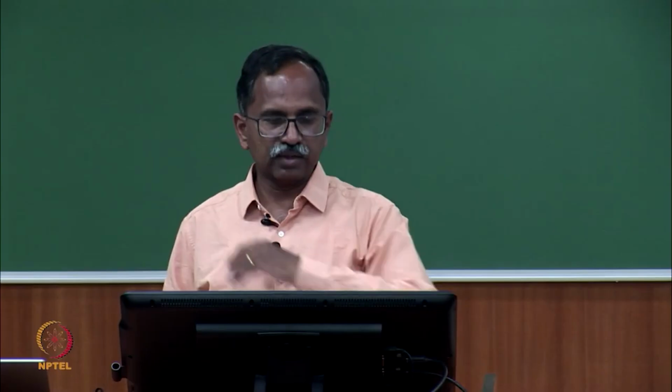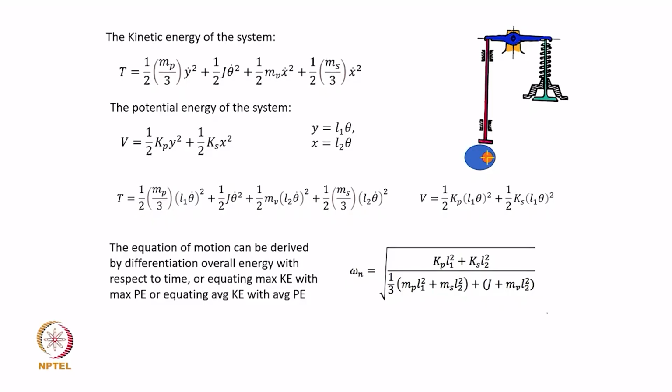So, if you really look at the overall vibration analysis process, we first looked at this physical system, considered all the possible motion, and we figured out that only degree of freedom here is theta, and then accordingly we got a simplified vibratory model. We used energy method in this case instead of Newton's approach or application of Newton's law to get the governing equation of motion and get the natural frequency expression from that. Once you do that,